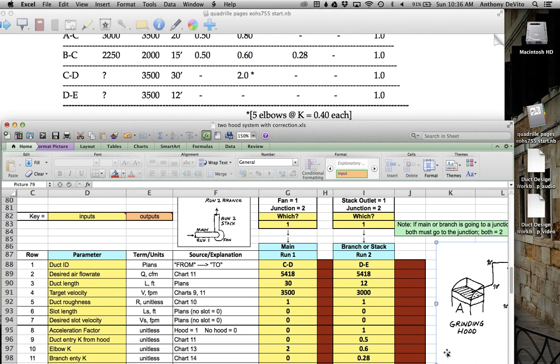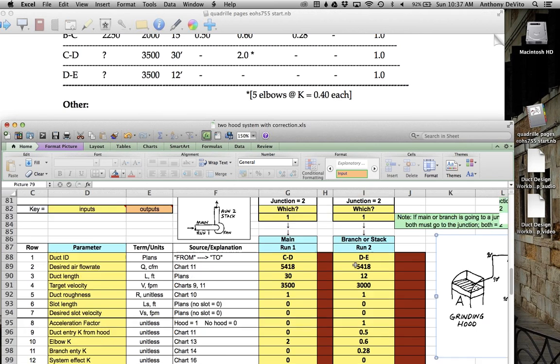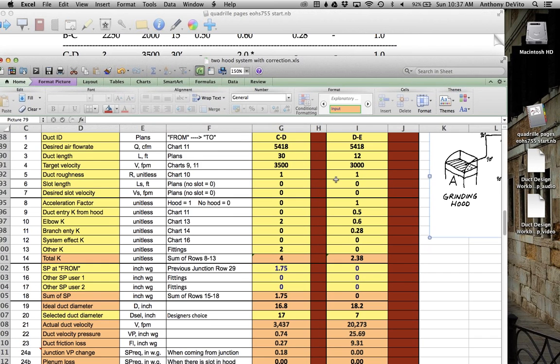And what's our desired flow rate? What's our target velocity? We've got some flexibility there. Okay, because I'm going to leave it at 3,000. I don't think they bring up here what they suggest, but we've gone through the air cleaner, so presumably a lot of these materials have been removed. I'm going to make a judgment call and just leave it at 3,000.